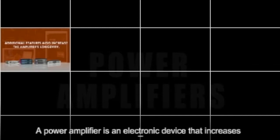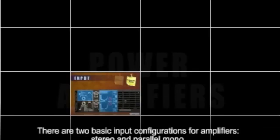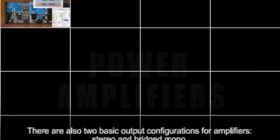A power amplifier is an electronic device that increases the line-level audio signal to loudspeaker level. Power amplifiers differ by way of their class, power rating, and number of channels. An amplifier's output is dependent on the impedance load of loudspeakers connected to the output and the input voltage level. There are 2 basic input configurations for amplifiers, stereo and parallel mono. There are also 2 basic output configurations for amplifiers, stereo and bridged mono.